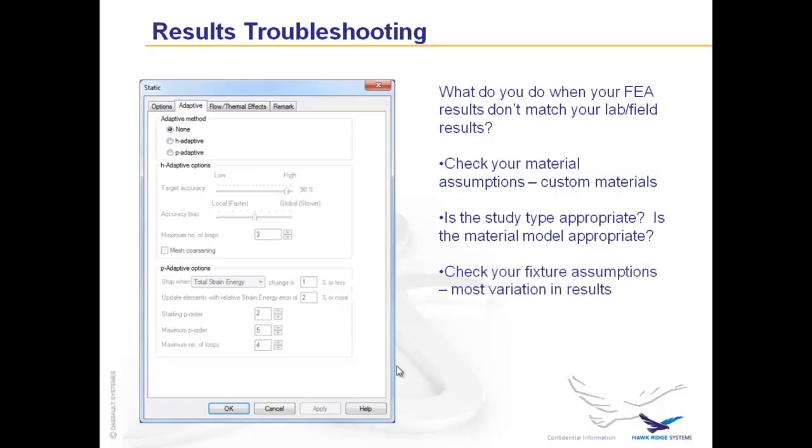Also, check your fixture assumptions. Now, you can check your loading assumptions and your connections, your bolt connectors and things like that, but your fixture assumptions are really where you're making the largest assumption, and you'll get a big variation in high stresses or stress concentrations.